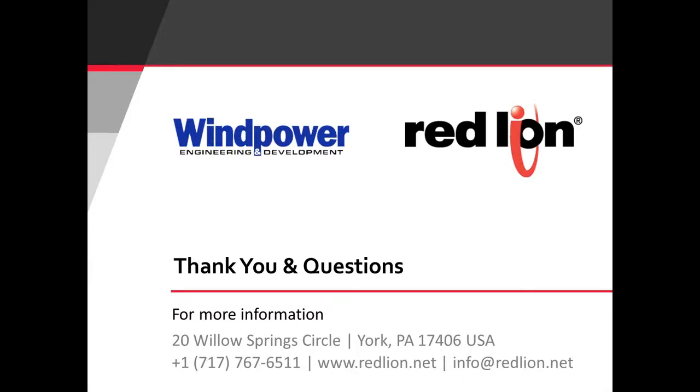I see. Okay, good. And another reader asks, with these rings of networks, is it possible for somebody to check the wind farm by internet? Absolutely. Managed switches typically have a web browser, and even through the NView capability that we talked about through the OPC server, they can monitor those statistics remotely. So again, health check packets on the ring show whether there's a ring break, and NView shows lots of information about dropped packets and collisions and the amount of data being transferred in general, including how far the switch is being used to capacity by port.